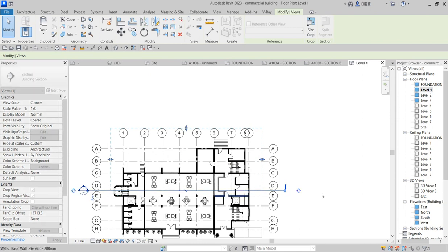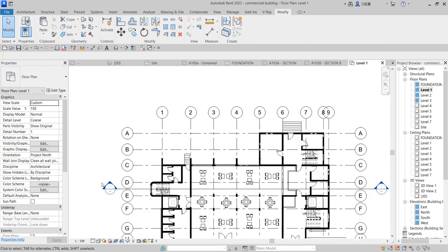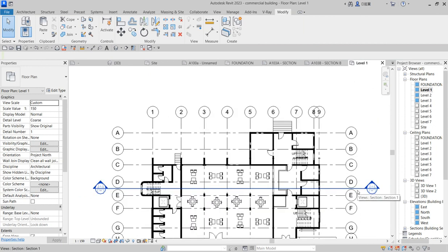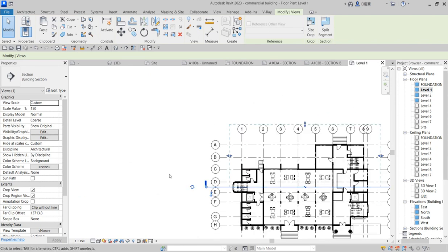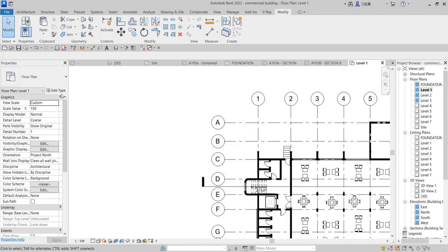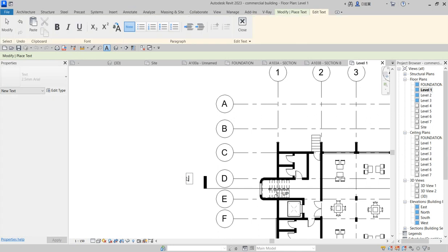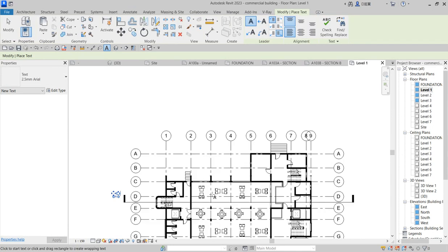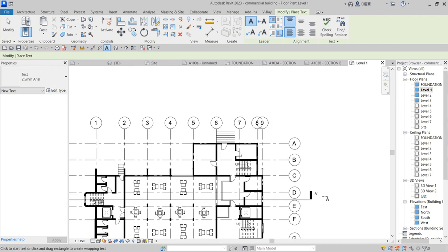So if this is too long for you, you reduce it. And if you want to have the double arrowhead, you click on that, so both sides will have arrowheads. If you don't want them at all, you click on them, select, and change the pattern in which they are. You can click like this. So you write your own personal label like AA. How do you do that? You can go here and say annotate, then you say text. From here you put A, section A, on this. At the same time you write A with an apostrophe, then that's it.